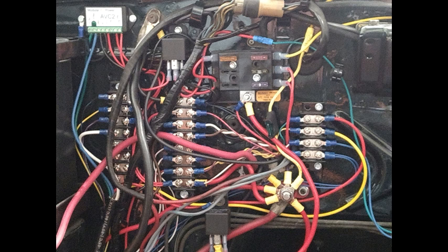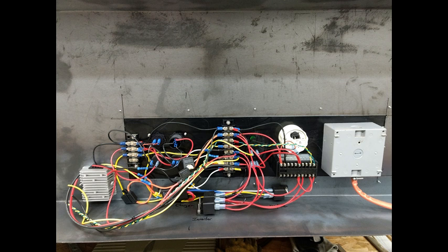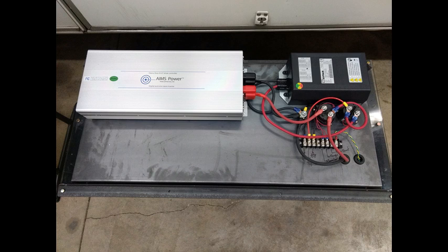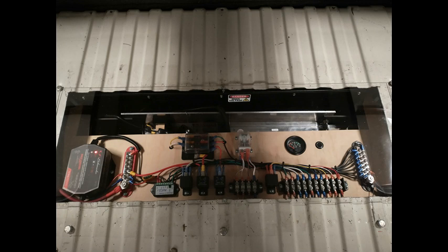If you use too small a wire for the load, the wire can get hot and cause problems. There's charts available on the internet that provide the current rating of the wire based on its type, size, and length. The resistance varies based on the size, type, and length of wire. For example, the resistance of 10 feet of 16 gauge wire, this is copper, is 0.0396 ohms. And for 10 feet of double aught cable, the resistance is 0.0000762 ohms. So a lot less resistance for the double aught cable, the same length as the 16 gauge cable. The larger the wire, the less the resistance per given length.